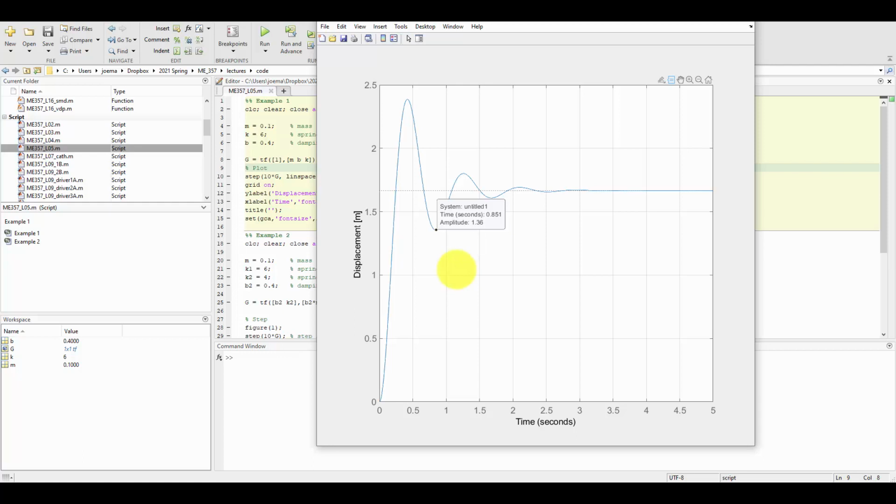Now notice here, x is strictly positive. In this case, it never goes above the equilibrium point under these circumstances. Then it goes further away, but only up to that smaller amplitude, about 1.8. It comes closer, goes further away, and then it settles in because energy is being lost as it moves. It's being dissipated through that viscous damper, and eventually it settles to its steady state value, that 5/3.